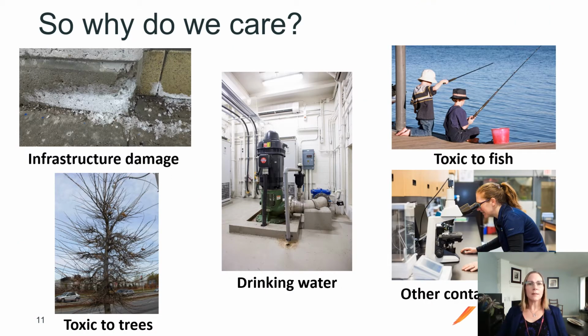We're not just interested in salt for the sake of salt, though. It has a lot of impacts on the environment. It can harm drinking water and is particularly risky for people with sodium-reduced diets. It can damage trees, buildings, and at extreme concentrations can be toxic to fish and impact aquatic food webs. And perhaps most concerningly, high salt concentrations can mobilize other contaminants, including heavy metals, and can reduce the effectiveness of the tools that we use to manage urban runoff. For example, our research over the past couple of years is showing that salt-laden water is reducing the effectiveness of stormwater management ponds to improve water quality.